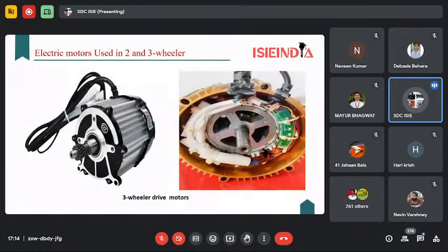So this is a normal BLDC motor which has a 12 kilowatt power rating, and I will show you where the Hall effect sensor is. This white one is the Hall effect sensor, which will detect the position of the rotor, and there are 5 wires for the sensing part, which work on a 5 volt power supply. And along with this, all 3 wires are connected for creating poles for the stator part, and at the center is a north pole. This one is a south pole. It is not easily identified.